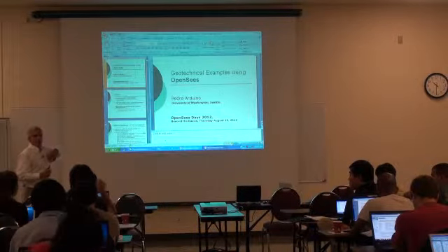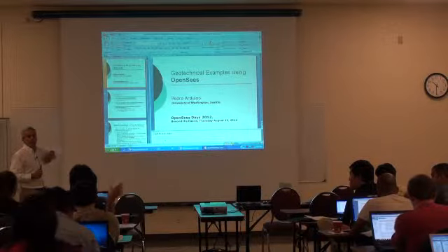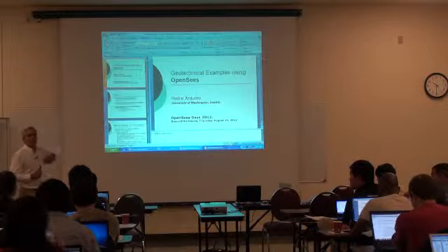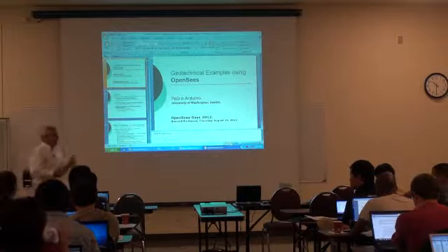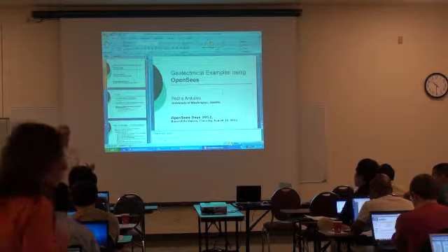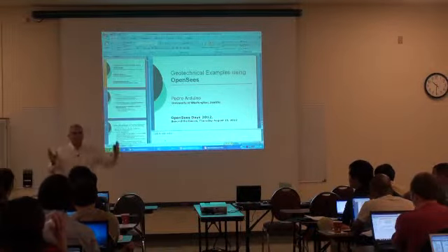One more about the absorbent boundary. You showed some formulation for the dashpot and the properties of the spring. Is it the same for 2D or for 3D? It's the same for 3D, but you will have three directions. Now, you have to be careful. This is based on Lysmer. Which year, Boris? Lysmer 1960, or even before that, 1950.